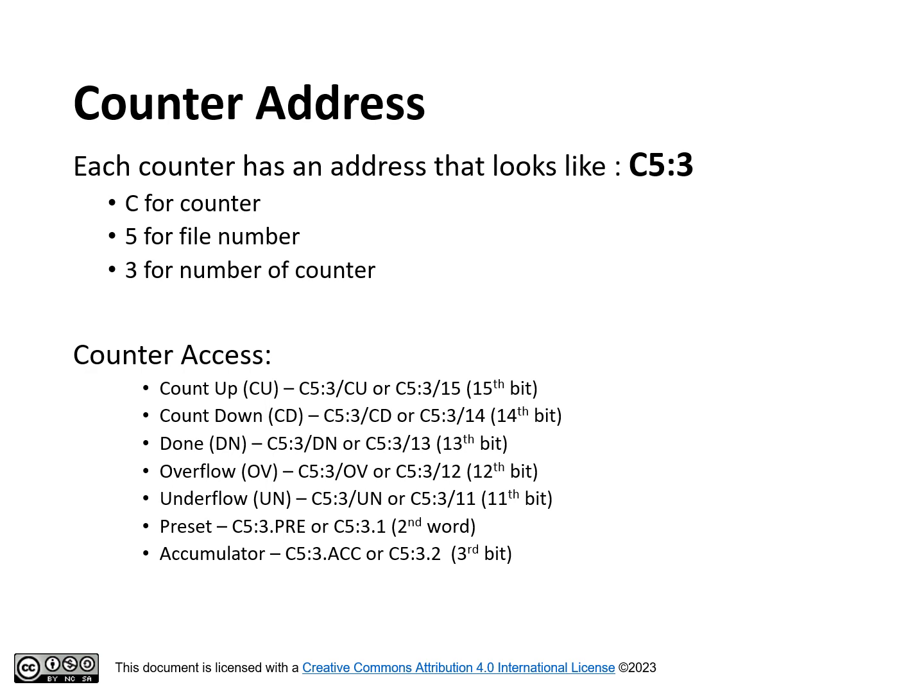Count up, CU, C5:3/CU, or C5:3/15 on the 15th bit. Count down, CD, C5:3/CD, or C5:3/14 on the 14th bit.